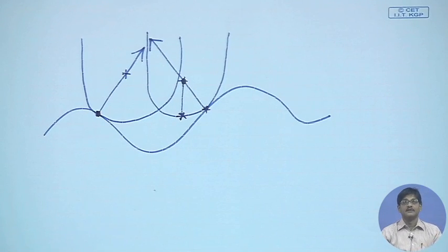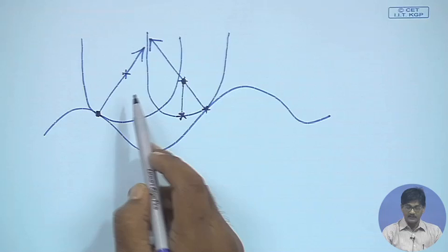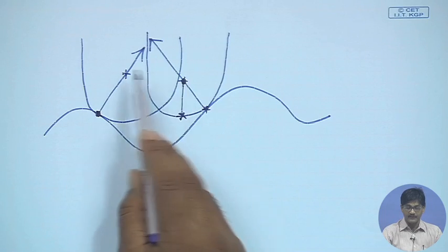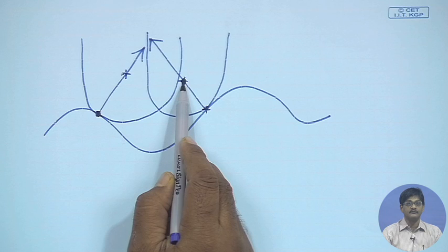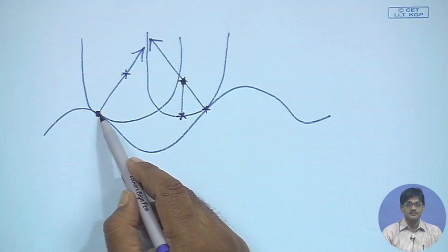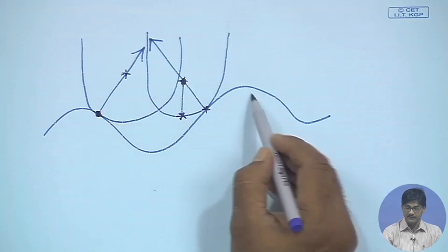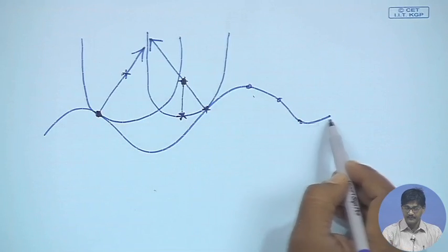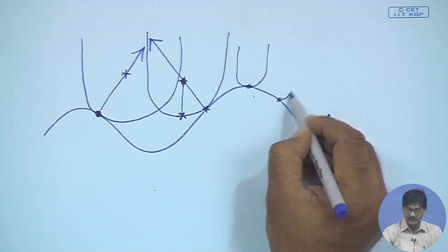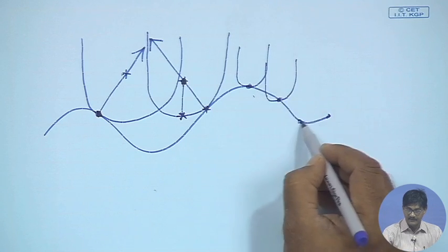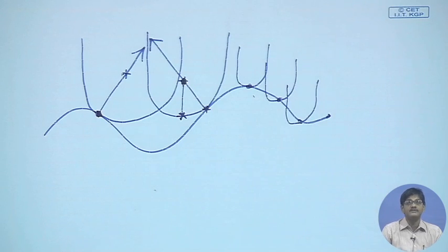That is it. So, I can draw the cutter uniquely once I have defined the position of some constant point on the cutter. Just giving the CC point is not enough. If I give you a series of CC points and you draw, okay, this is the cutter, this is the cutter, this is the cutter, all these would be wrong.